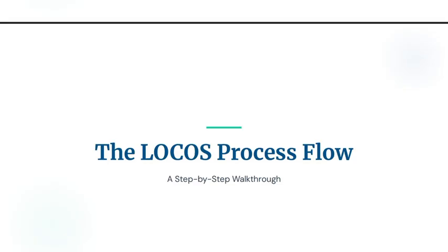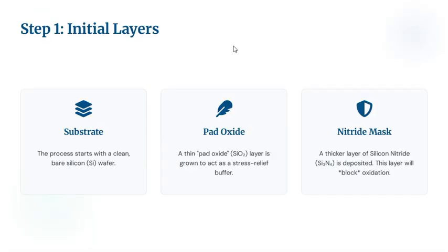So, coming to the LOCOS process flow, let me first speak about the initial three steps. We will have a silicon wafer. This silicon wafer will consist of a p substrate. In that, an N well might or might not be present, and the diffusion regions, which are the more crucial part for which the LOCOS process is being carried out.